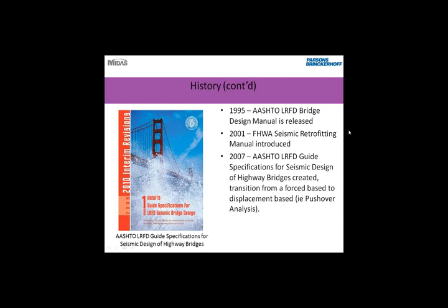For those of you that are from the Northeast, I'm from Connecticut, and if you drive along I-84 through Waterbury, you'll notice where the Route 8 connector is, there's a multi-level ramp structure, and those are all retrofitted with restrainers and extra reinforcing on the piers. So I think this is quite a common practice nowadays.